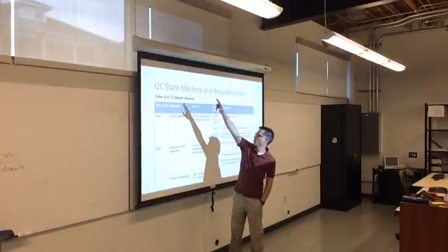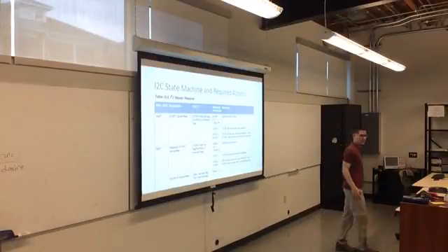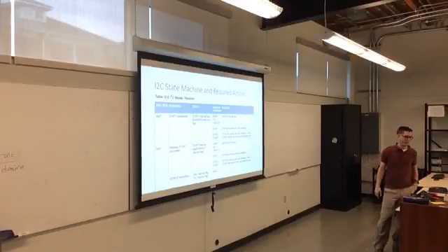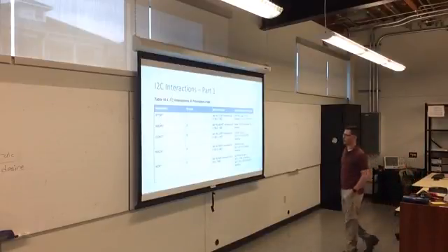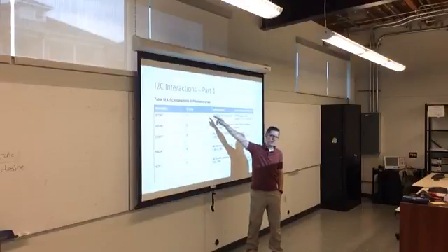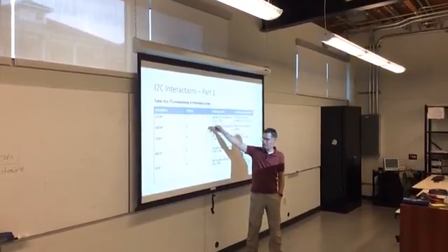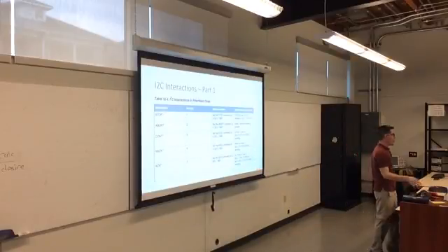And again, the interactions have priority order, so if at any time you say stop, a stop will get sent before an abort will be sent before a NAC or an ACK. So they have priority on them, but you'll only really ever be doing one command at a time. Okay, this can be really confusing, but we're going to simplify it in one of two ways.